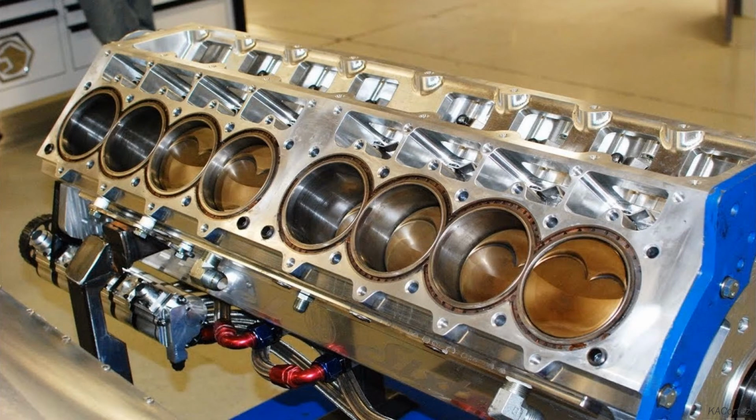Next is the crankcase. It is the housing for the crankshaft. In most modern engines, it is integrated into the engine block. It is the foundation of a reciprocating engine, and it contains the internal parts and provides a mounting surface for the engine cylinders and external accessories. It is made of cast aluminum alloys.